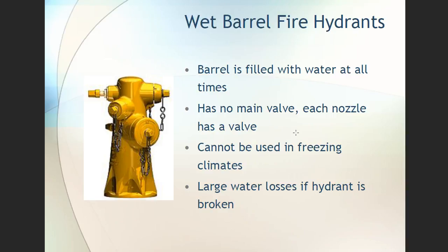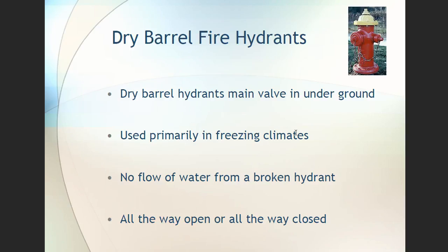I've lived in a lot of cold climates, and the hydraulic pressure of freezing water is just phenomenal. If there's water in here and it freezes, it could be 2 inches thick cast iron, and it'll go ahead and break it. Unbelievable pressures with the freezing and the hydraulics. Dry barrel hydrants, the main valve is under the ground. It's used primarily in freezing climates. There's no flow of water from a broken hydrant, and they're either all the way open or all the way closed.